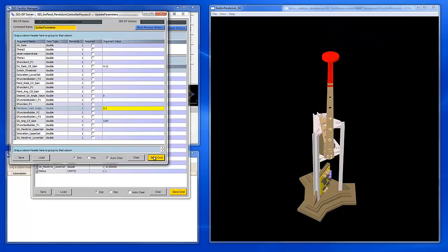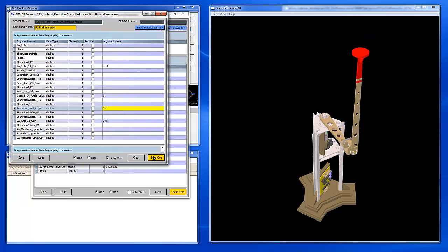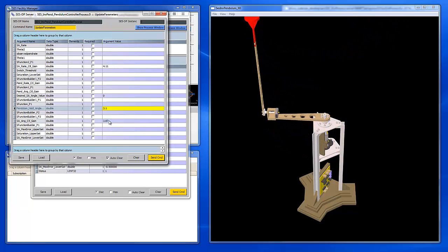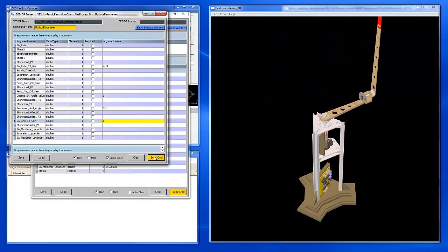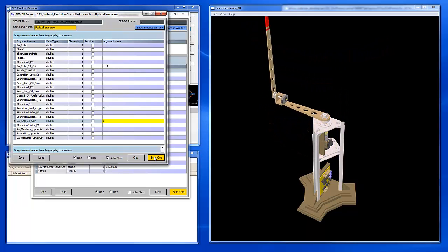You'll notice a slight disturbance in this case as the swing arm passes through pi radians. This is because the swing arm error signal changes sign at this point. To remove this disturbance from the system, we can set the swing arm position gain to 0. The system now transitions through this position without issue.